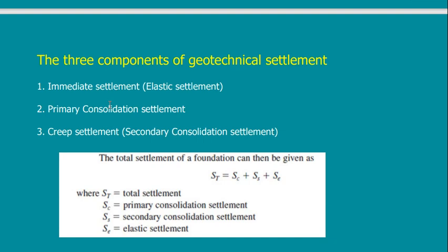This little bit may be days, it may be months, and it may be years. Some buildings would stay something like 70 years in consolidation period. So this is what we call consolidation settlement, or they later called it primary consolidation settlement because they discovered that consolidation itself happens in 2 stages.